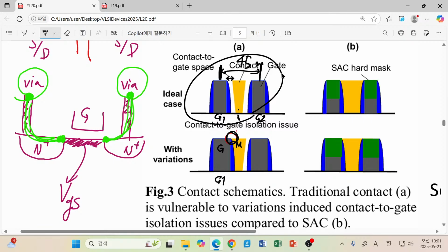Since the overall size is 25 nanometer, and please note that once again, if this is 14 nanometer, this is corresponding to 7, and this is corresponding to 7. Now we have 14 subtracted from 45, so we have just 31 nanometer for placing our source drain metal precisely at the middle of this 31 wide structure. And if we make any offset or shift of this placement, then such kind of isolation issue can happen.